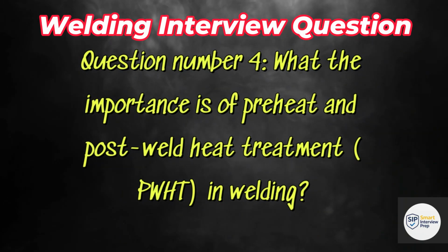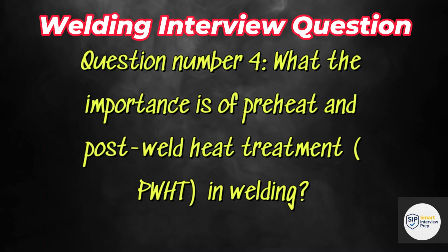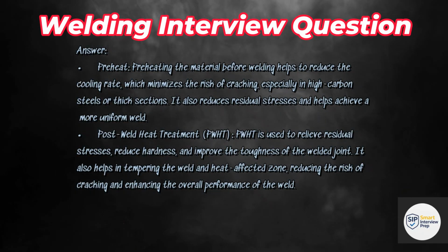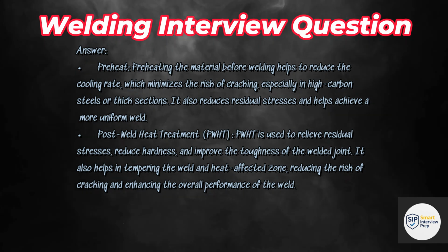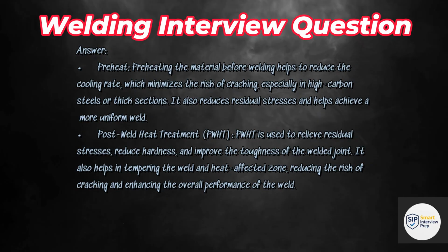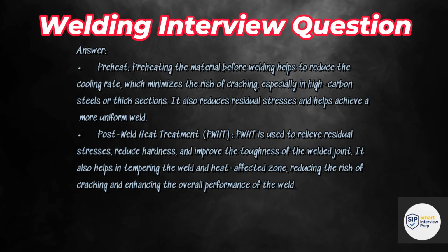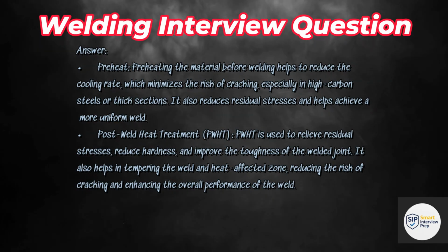Question number 4. What is the importance of preheat and post-weld heat treatment, PWHT, in welding? Answer. Preheating the material before welding helps to reduce the cooling rate, which minimizes the risk of cracking, especially in high-carbon steels or thick sections. It also reduces residual stresses and helps achieve a more uniform weld.